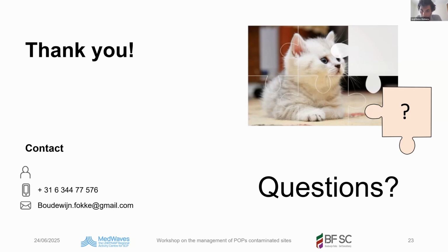Yes, and the last one is how do CSMs reflect dynamic site conditions or long-term change? For example, seasonal groundwater fluctuations, contaminant degradation. What is the solution in this case? Do you have an answer for this? Yeah, you have to be aware of long-term changes and dynamics in your sites, for instance of the degradation processes, and make use of them in your remediation assessment.